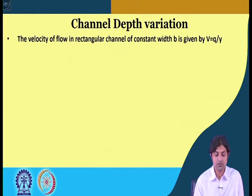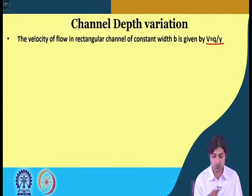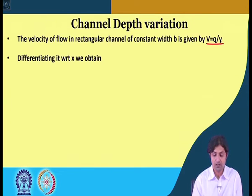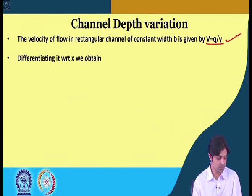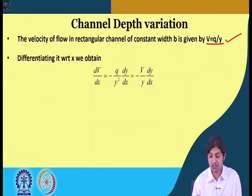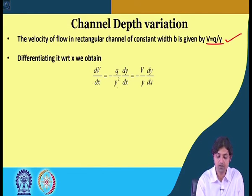The velocity of the flow in a rectangular channel of constant width b is given by V equals small q by y. If we differentiate this also with respect to x, we can obtain dv by dx is equal to minus q by y square dy by dx.